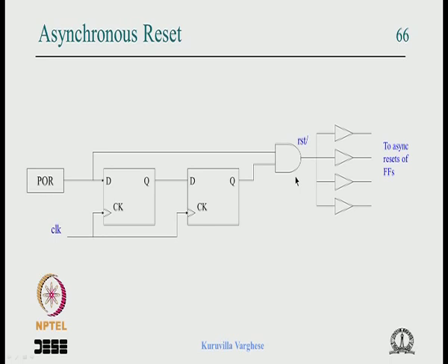As far as the active low signal is concerned, we studied this at the beginning. If you remember, we looked at the difference between the AND function and the AND gate. Now this is an AND gate doing an OR function for an active low signal. For an AND gate whose inputs and outputs are active low, it is doing an OR function, and we discussed this in the overview when we reviewed the basics. I told you at that point that this brings the De Morgan theorem into our concept.